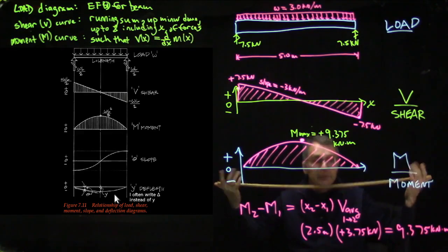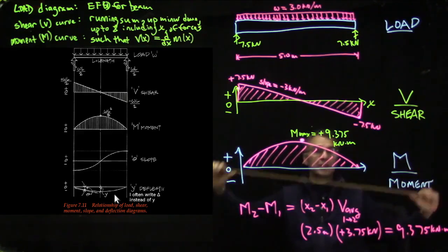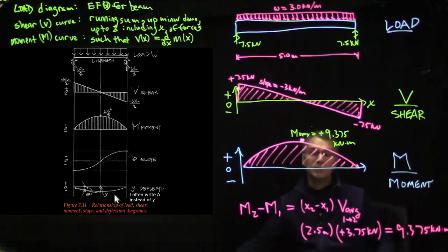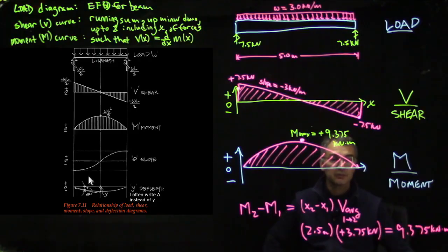Or a cantilever is deflected downward at the end. So it's saying when you stick the weight on the beam, how does the shape of the beam change? So you integrate the moment once more to get this angle, and you integrate that angle once more to get this deflection. So what we're going to do in the next video is to argue why it makes sense that integrating this moment diagram 2 more times gets you the shape of the deflected beam.